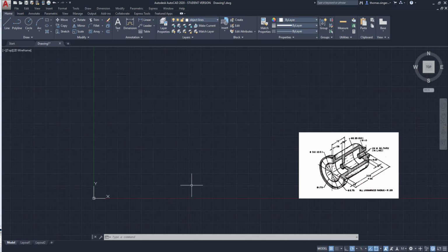So with that being set up, we have our line type layers. Down on the bottom, we can set up our grid and our object snaps. Right now, we have polar tracking set up, which is fine, because we're going to be doing primarily a linear drawing. Typically we'll set polar tracking at 15 degrees. You can go as low as 5, but since everything we're doing is going to be more or less linear, 15 is fine.